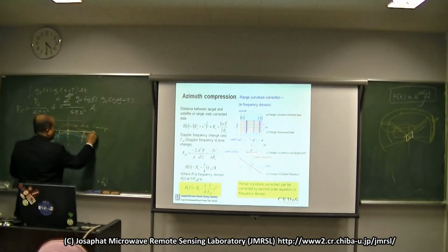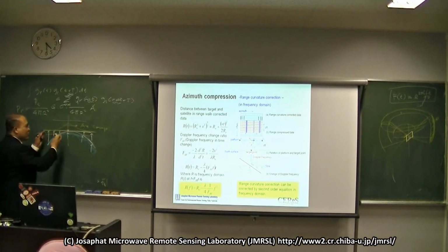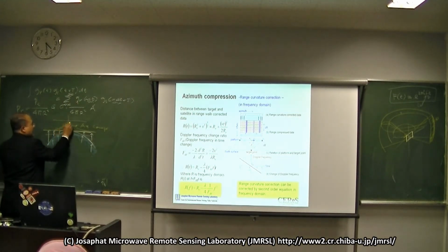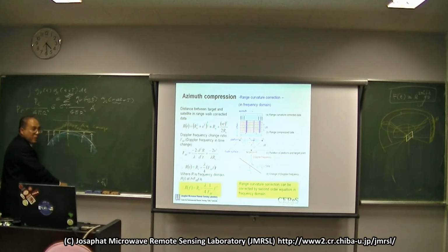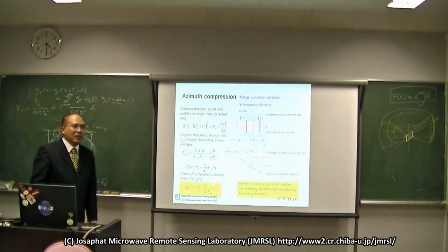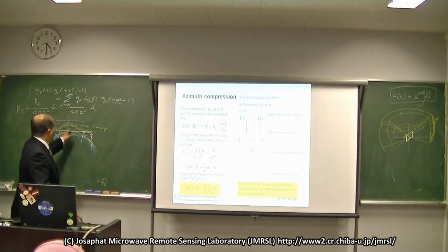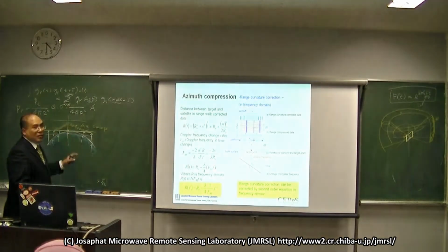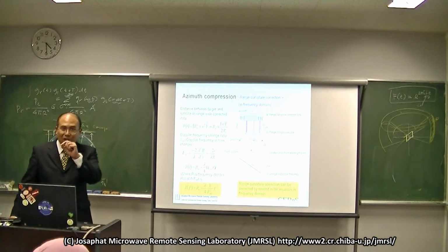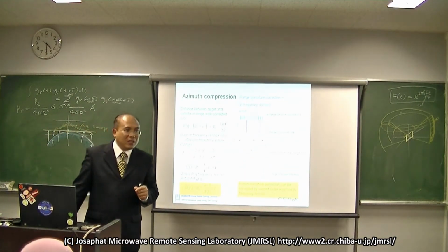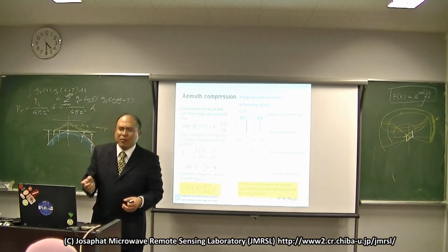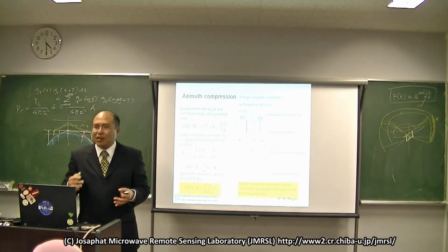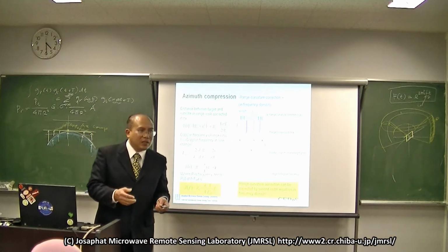In some papers, you smoothen first, then only interpolation. Because if you do this without the filtering, I think your phase information will be affected by the noise, and if we use this data for InSAR, it will drop the quality of our InSAR.